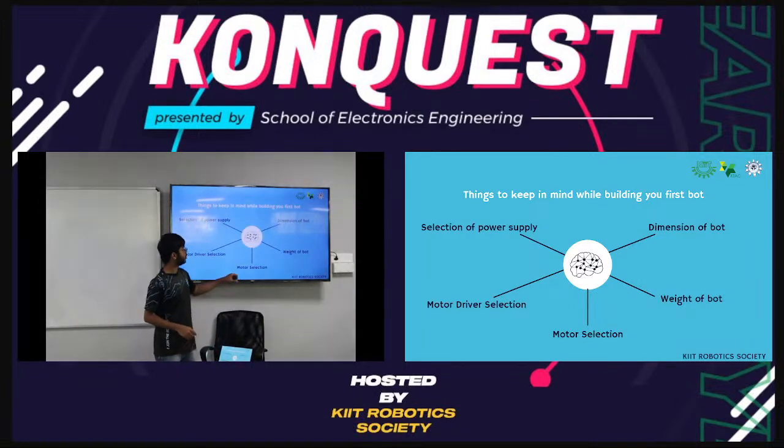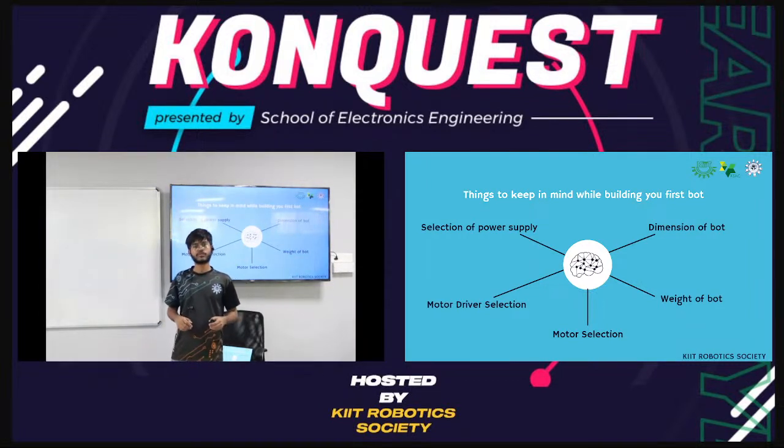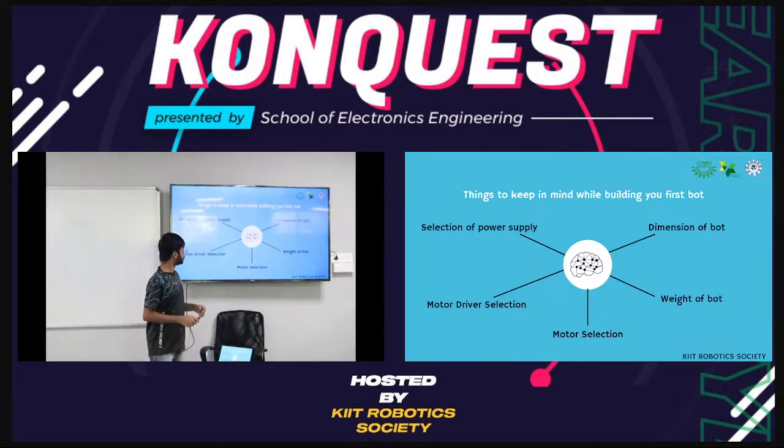Next, we will be seeing the weight of the bot. If your bot is heavy, then you need motors powerful enough to carry the bot. And if it's small enough, then you don't need those higher energy motors. Accordingly, your motor drivers will also be changing depending on the current draw.